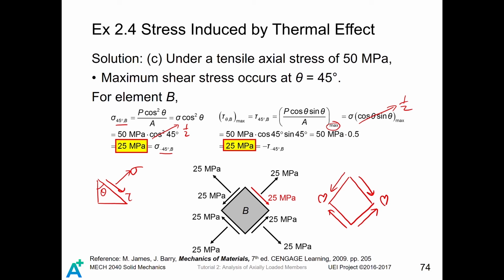So the shear stress is sketched like this. Since we have computed the shear stress on the 45 degree outward surface, which is 25 million pascals, we know the rest of them are all of magnitude 25 million pascals. Then that's it. This is how we sketch this stress element. To sketch the shear stress, first you get one of them. Then by using the principle of kissing, or the Valentine's Day joke, you can sketch the shear stress on a stress element.